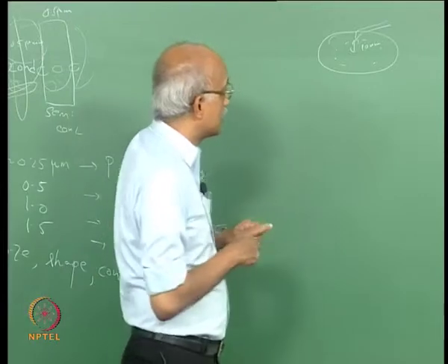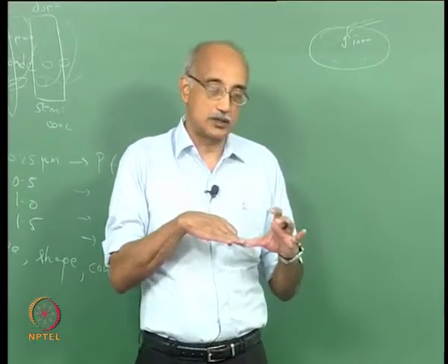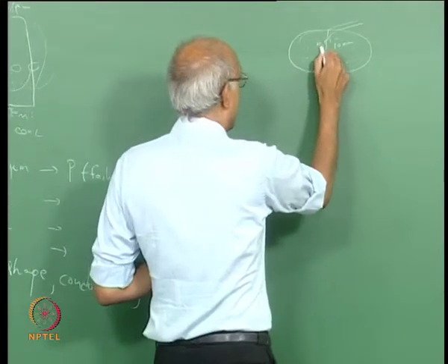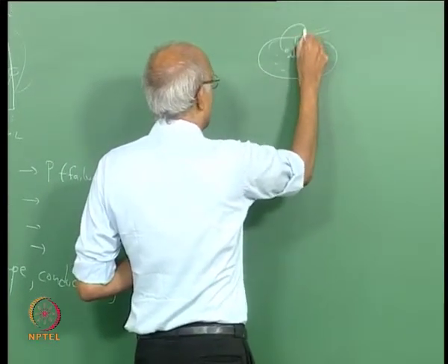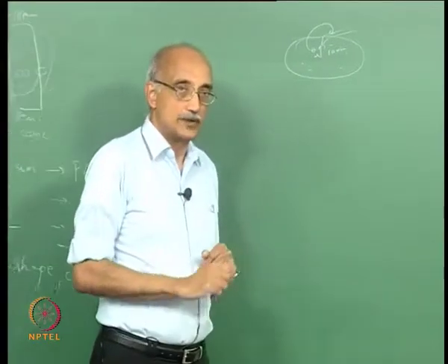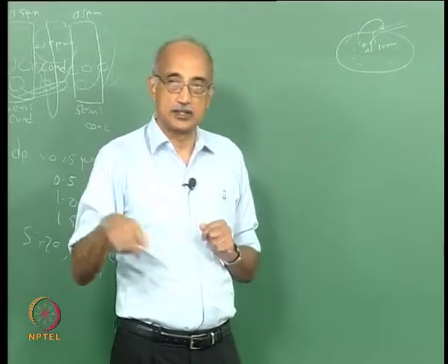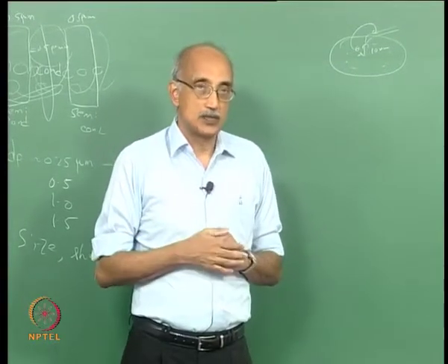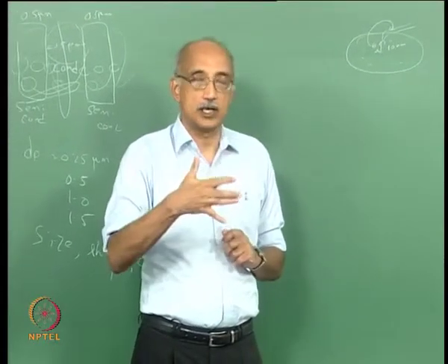Another thing that can happen is as the head flies over the particle, it can get scooped up by the head, so that a particle that may be sitting on the disk, because of the airflow, now collects on the actuator mechanism that's driving the heads. Then what happens? It causes a change in the trajectory of the head.